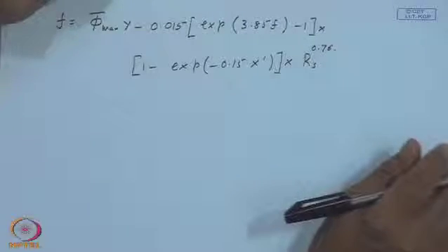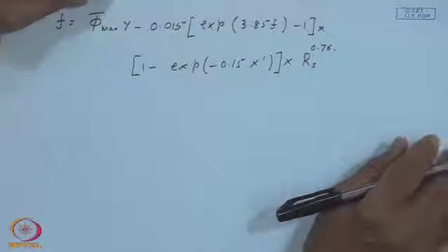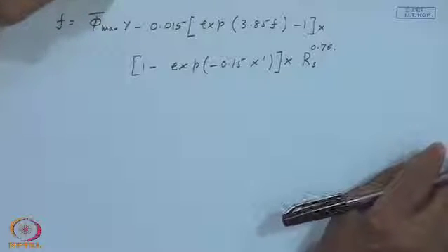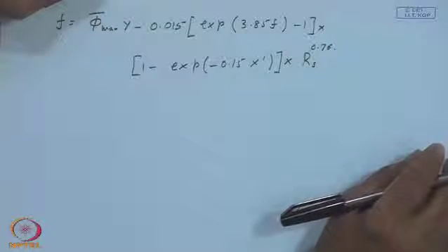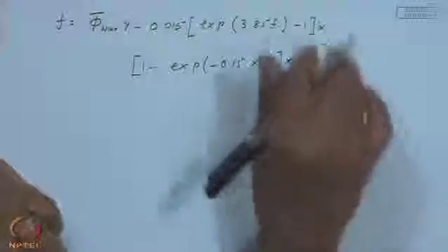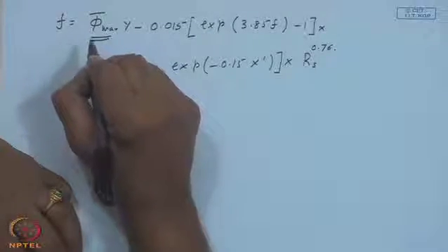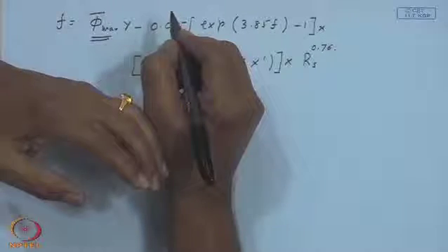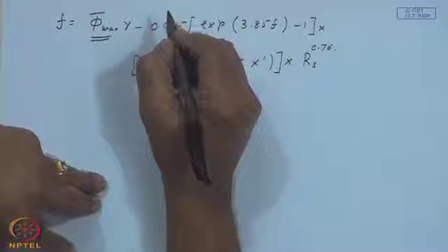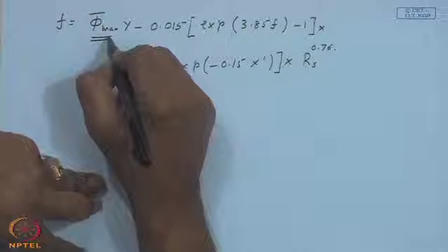We have done up to here, and we tried to describe how to include the tank losses also, in brief, in the last class. But my whole idea is that the philosophy behind this phi bar F chart method is to relate the temperature at which energy delivery is desired to the minimum temperature and a quantity called utilizability, which indicates the solar radiation available above a certain critical level.